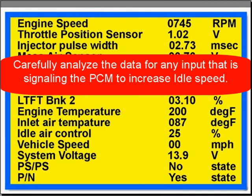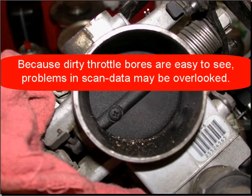Carefully analyze the data for any input that is signaling the PCM to increase idle speed. Because dirty throttle bores are easy to see, problems in scan data are often overlooked. Don't be the one who overlooked the incorrect scan data.